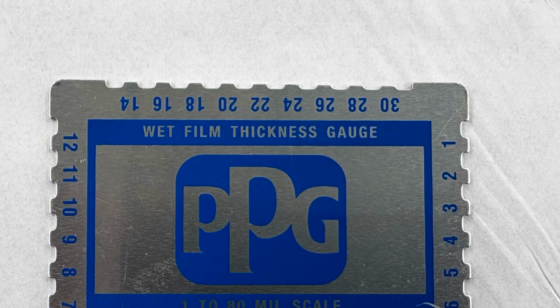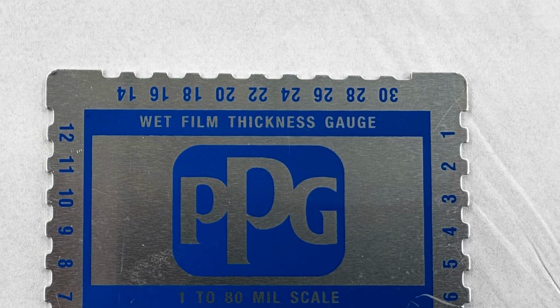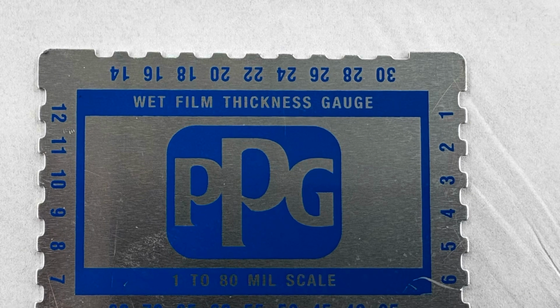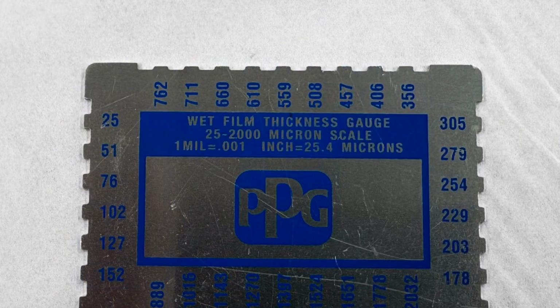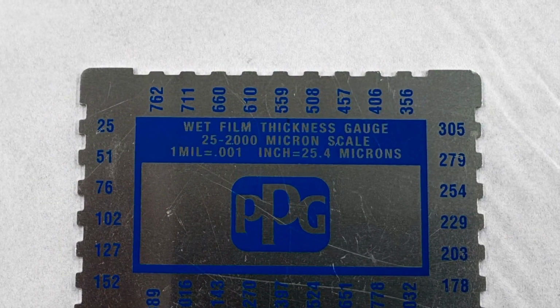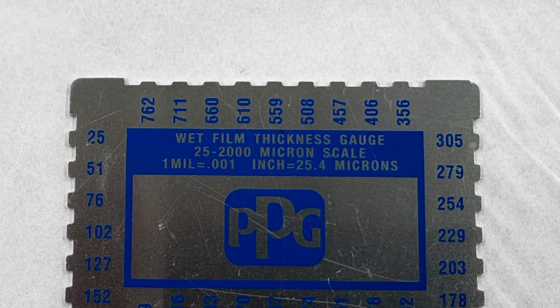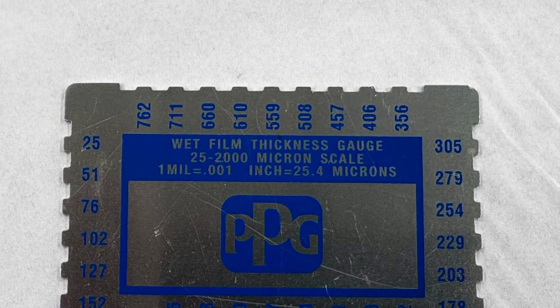Paint film is typically measured once it's dry, but using a tool like this, it can be measured while it's still wet. On the back side of this gauge, you'll see some other measurements that include microns. Microns are a measurement that we don't typically use in North America, as we typically revert back to the mil measurement referring to 1/1000th of an inch.